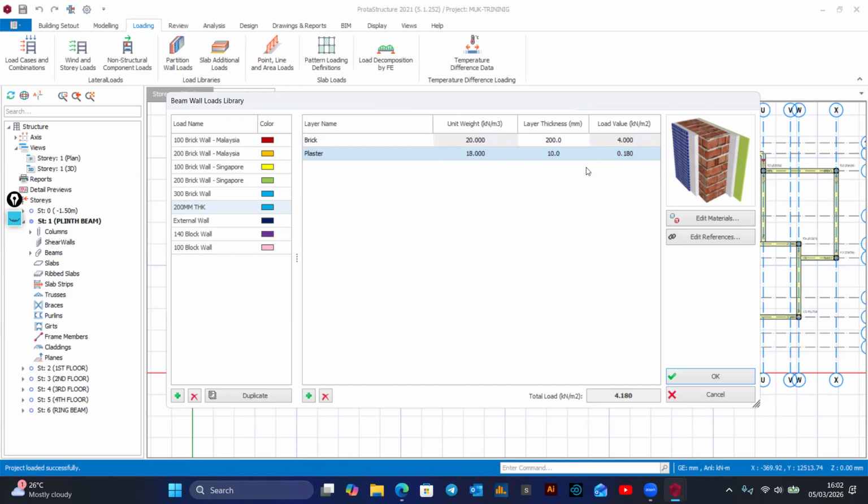Okay. So now, what the architect has indicated is 200 on the architectural layout. They expect that the total thickness of that wall is going to be 200. Then as you're designing, you need to factor that in by reducing the thickness of the bricks here. Let's say you can put it at 190 and you have plaster on one side of 10 mm, to keep within the thickness which has been defined on the architecture.